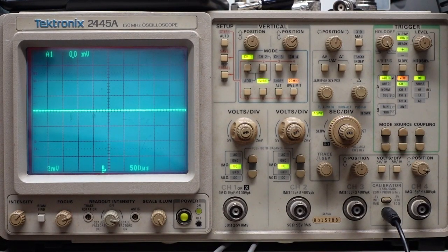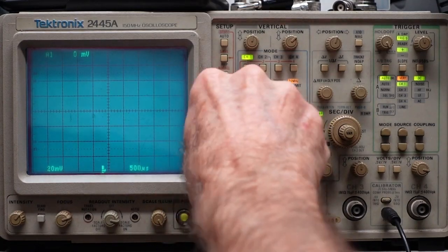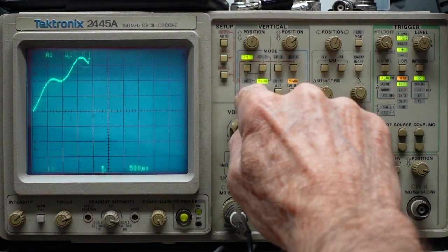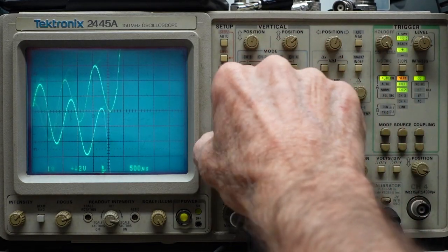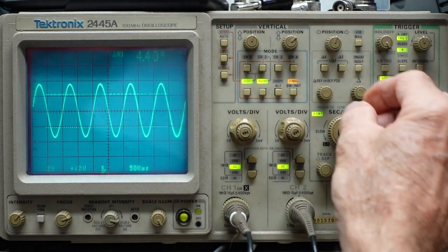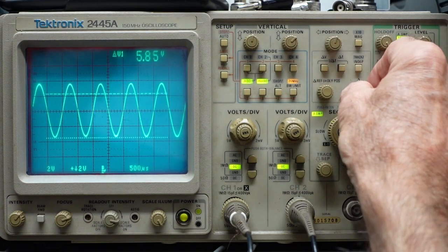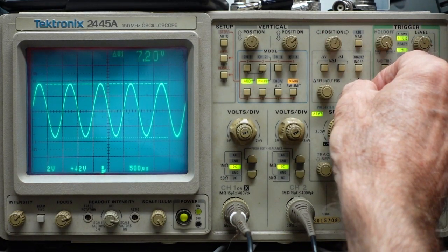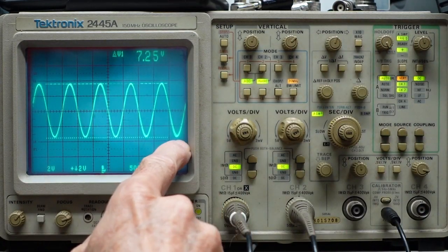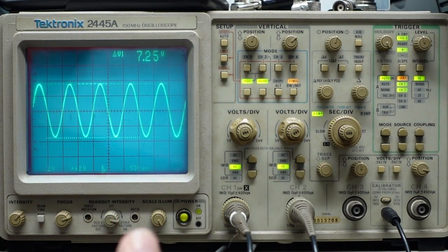One thing that this oscilloscope does that others may not is it does what's called cursor measurement. And I'm going to connect our probes back up again. If we have cursor measurement on, it puts these cursors on the screen, and I can move them into position, and then I can read my peak-to-peak volts right off the screen here. Your scope may or may not have that. Digital scopes you can just set up and it'll read it without having to use cursors.